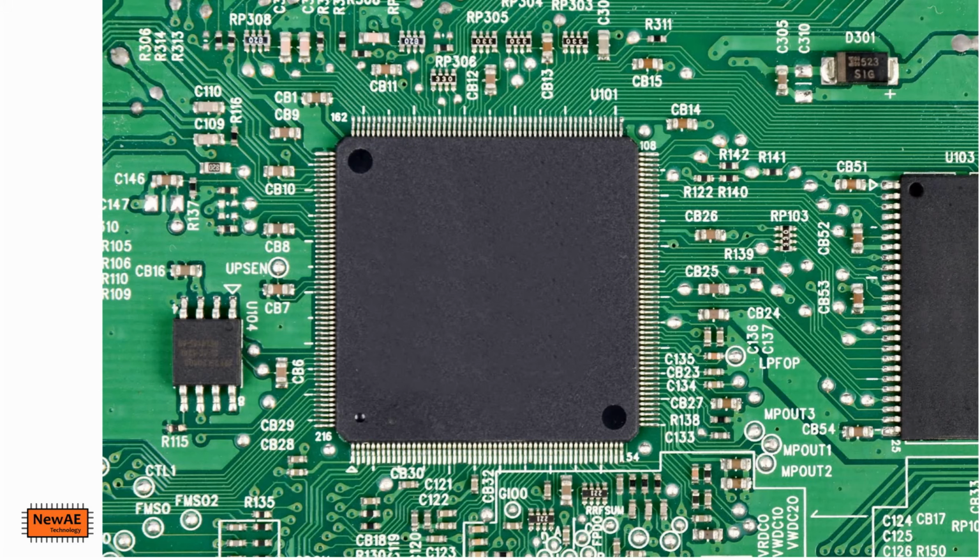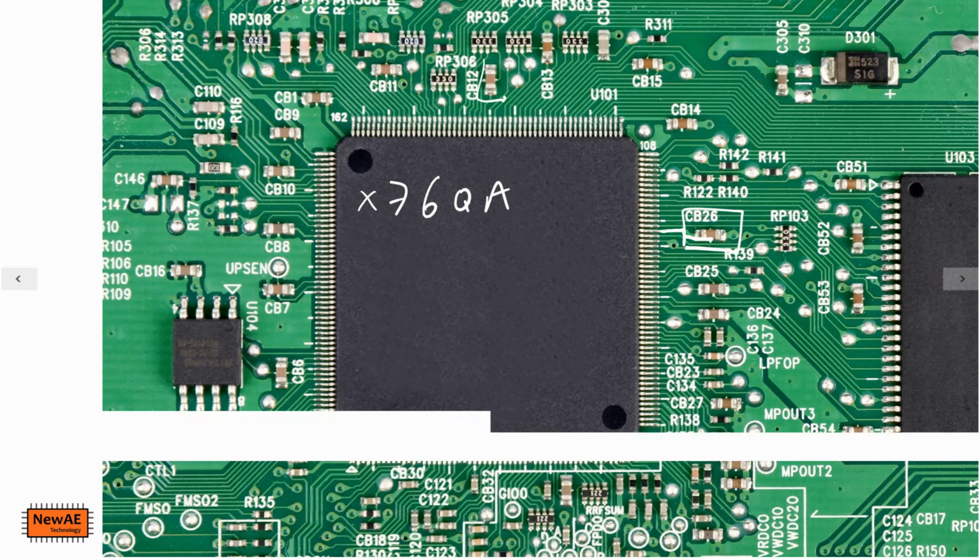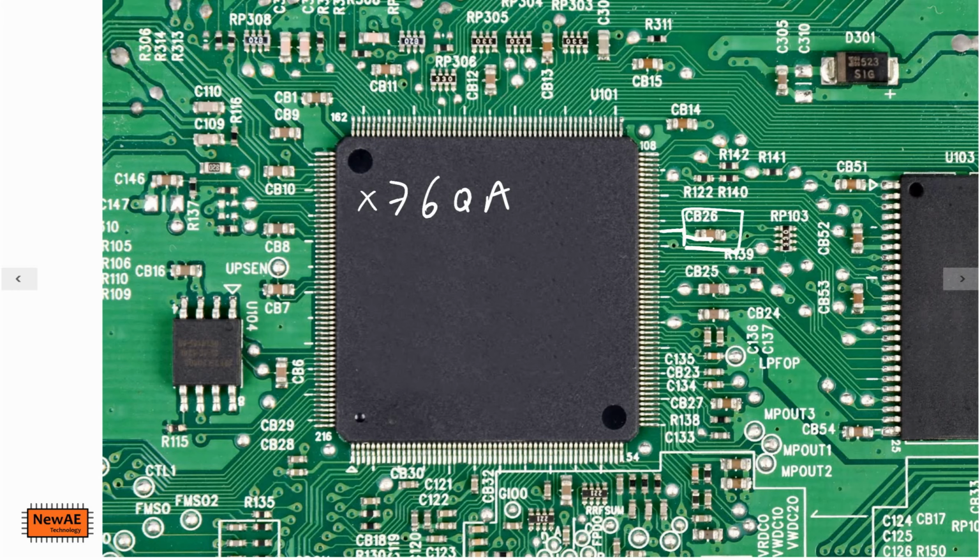This is where a bit of engineering and investigation is needed. For example, there may be numbers on the chip that give me the device ID, and I can go look up a data sheet and see what the power pins of interest are. I may just assume that these capacitors here are likely decoupling capacitors, so I can probably figure out which of these are power rails and which are not. Using the circuit board, I can figure out what the power pins are.